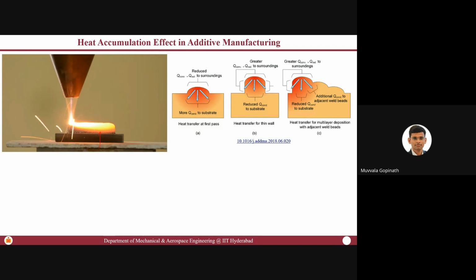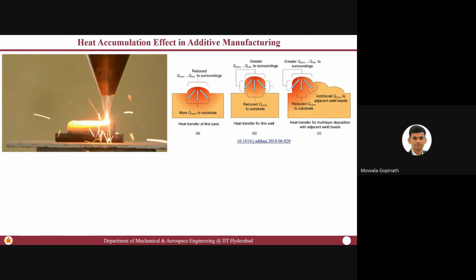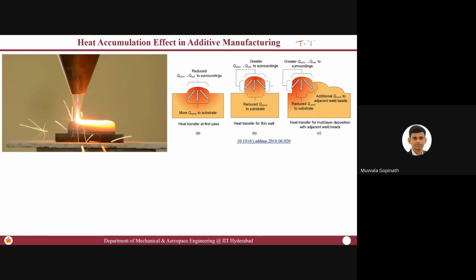One, if you talk about mechanical property, if you talk about surface property, it is a function of its microstructure, what we call TTT curves, time temperature transformation curves. If you look at this time temperature transformation curve, the microstructure essentially is dictated by how the material is cooling.